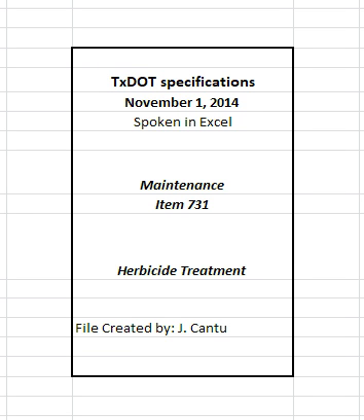7.2 Pavement edges, structures, and fixtures. Apply herbicide to eliminate all grass and weeds encroaching into or on pavement main lane, shoulder edges, riprap, and structures including retaining walls, sidewalks, islands, traffic barriers, raised medians, curbs, mow strips, and any other concrete or asphalt structure as shown on the plans, or as directed.